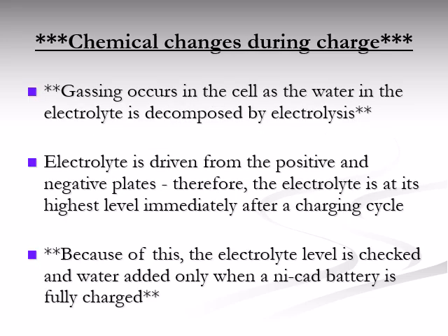Charging nickel-cadmium batteries causes electrolysis and gassing. Electrolyte reaches its highest level immediately after charging. Add water only when the battery is fully charged.